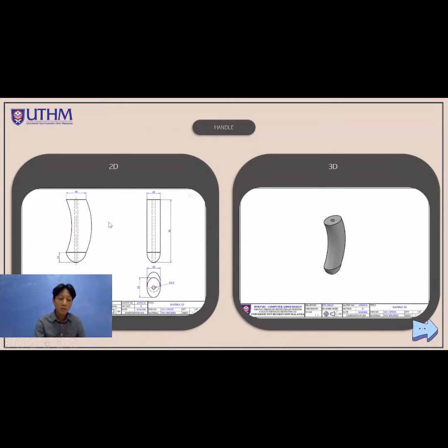Next we make a straight line upward from one of the centers of the ellipses using the line command with a length of 80 millimeters. Next we move the center of the other ellipse using the move command. We move it to the opposite side of the line. Then we make a curve or an arc on the edge of 15 millimeters of both of these ellipses by using the start and angle command with an angle of 30 degrees.